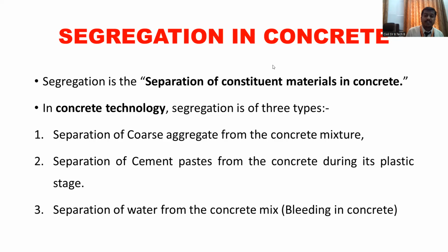First type, separation of the coarse material from the concrete mix. Second type, separation of the cement paste from the concrete mix. And third type, separation of the water from the concrete mix. That is what you call bleeding.